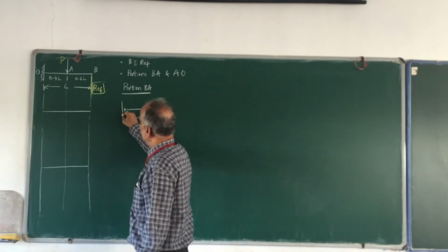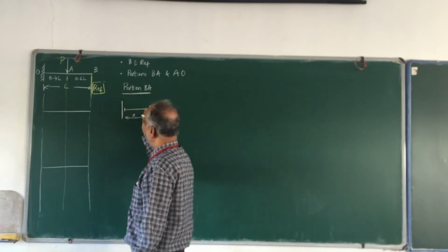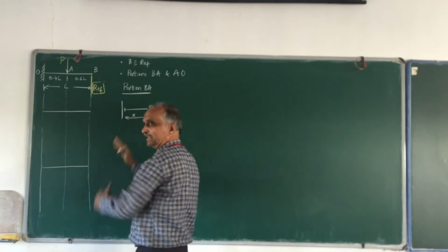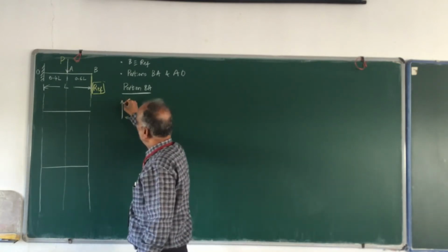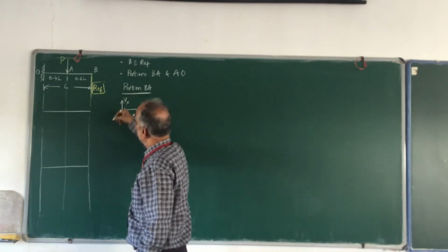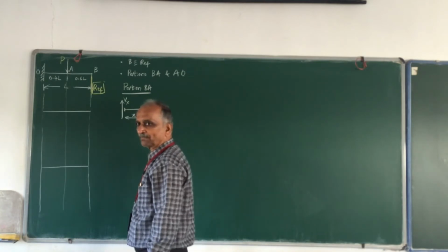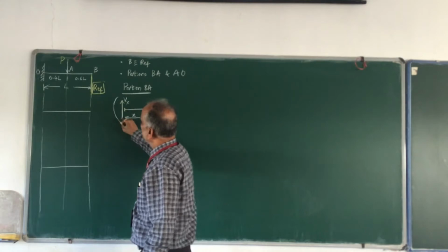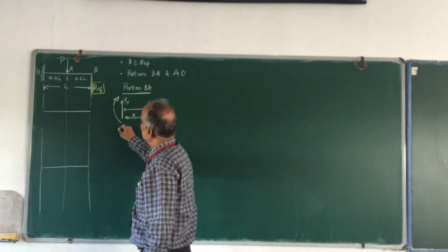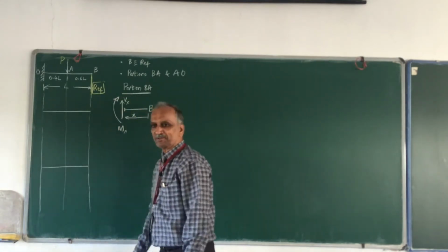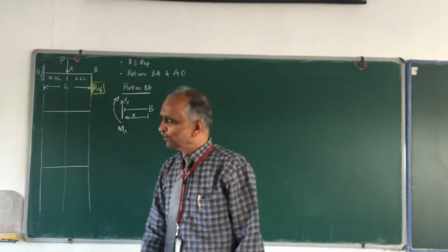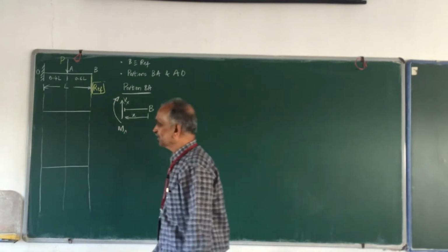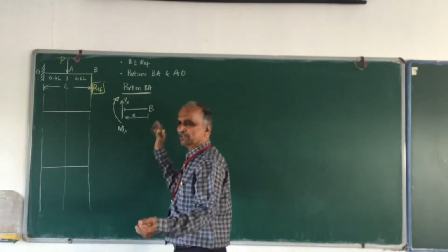Imagine the positive shear force. As you know, the beam portion you are considering for analysis is to the right side, and therefore upward shear force is positive. Let me call this Vx. The upward is positive, and similarly this is the bending moment which I am taking as positive Mx. You can go back and check what sign convention you have followed, and I would like to be consistent with that.